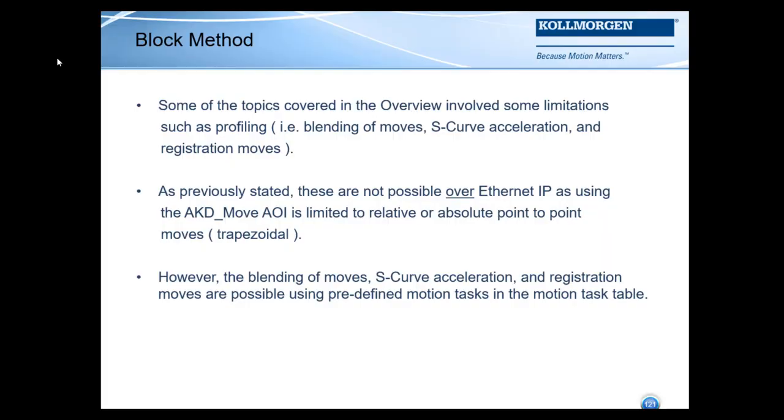Some of the topics covered in the overview involve some limitations such as profiling, blending of moves, S-curve acceleration, and registration moves. As previously stated, these are not possible over Ethernet IP, as using the AKD move add-on instruction is limited to relative or absolute point-to-point moves, which are trapezoidal. However, the blending of moves, S-curve acceleration, and registration moves are possible using predefined motion tasks in the motion task table.